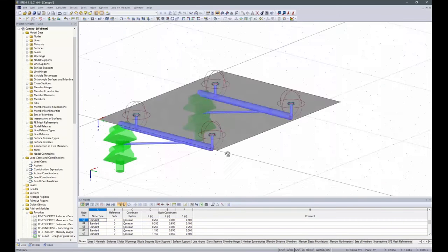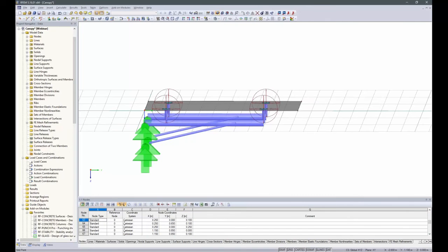So we're pretty much done, although the construction has to be modeled with an inclination of 5 degrees from the outer wall of the building, because water has to run down and snow has to fall down, so it's not supposed to be straight. We could rotate everything around 1 point, which would be okay, but this would result in other points being shifted sideways, which we don't want.